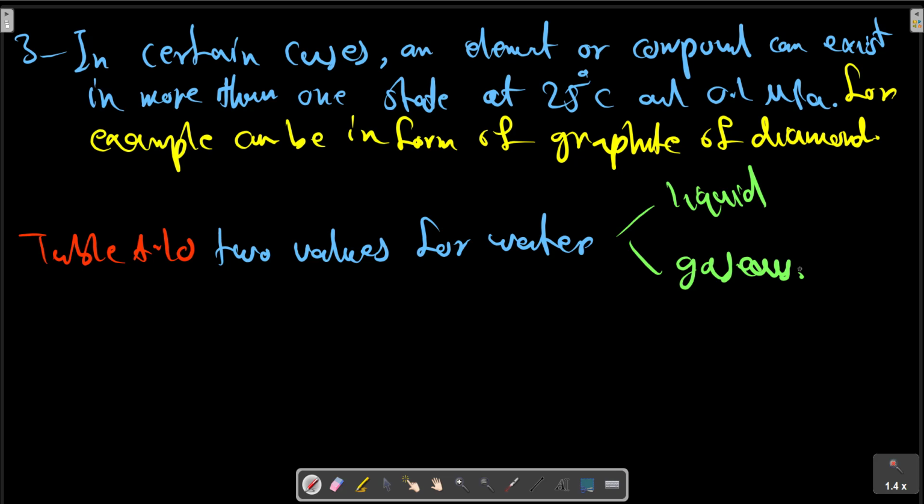The real liquid reference state properties are obtained from those of the hypothetical ideal gas reference by following the procedure of calculation described in section 14.10. The same procedure can be followed for other substances that have a saturation pressure less than 1/10 megapascal at the reference temperature of 25 degrees centigrade.